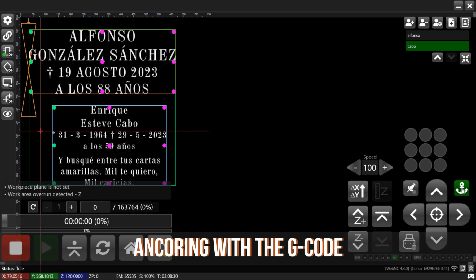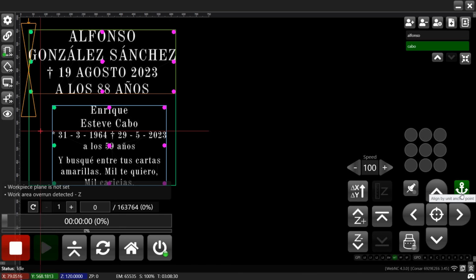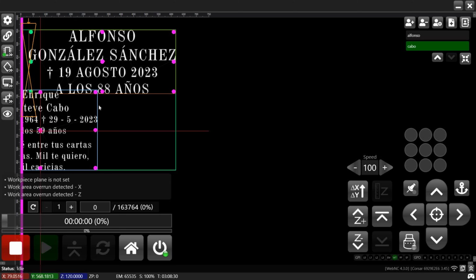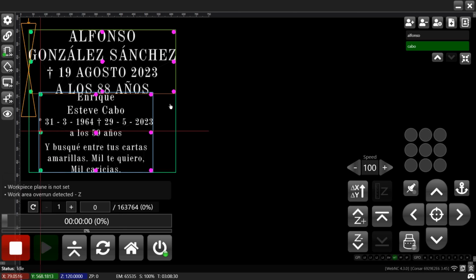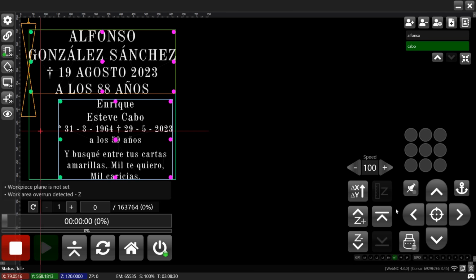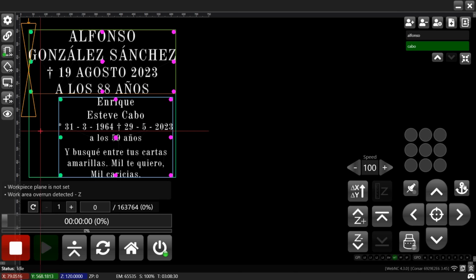By clicking on the anchor button, we once again use snapping by selected object. The difference is that this time we are using a different coordinate system, the one that is built into the G-code. This type of snapping may be tricky as assignment of point 0 may be different in different G-codes. For example, some may set a center point for a 0 while others may set the upper left corner. So one has to be certain why they want to use this particular option for binding objects.